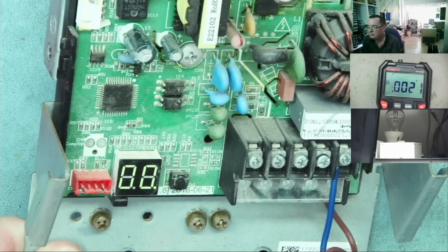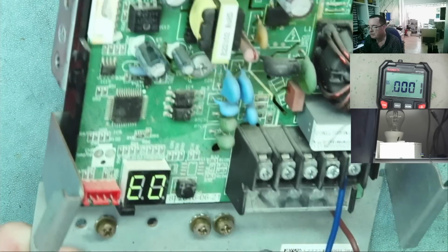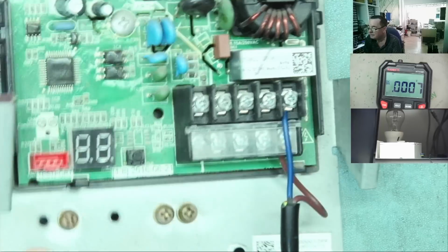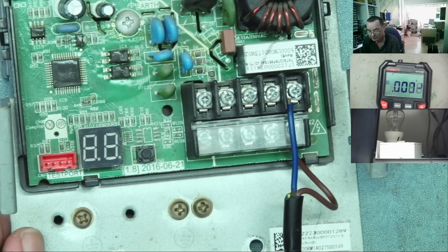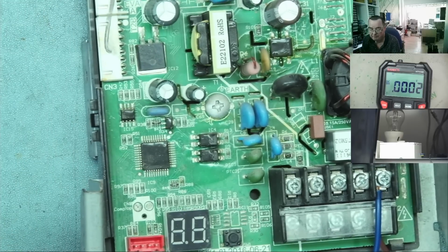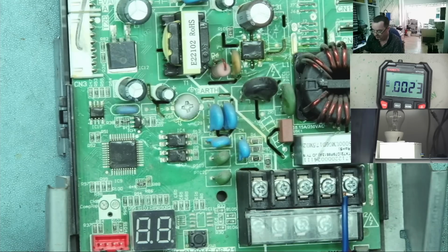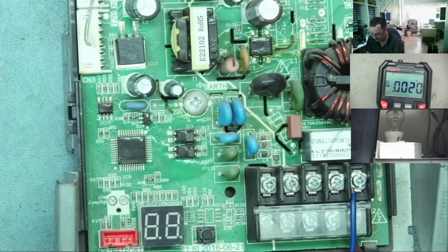Being an outdoor unit, that seems a bit silly if you couldn't see it, but I could not see that lit up. And yes, I know I had mains here because I measured it, I checked that on site. So maybe that's a red herring. Let's have a look at the other PCB, see if we can see anything obvious in the direction of that one. But with this one, well, the mains comes through to the output terminals and this powers up and runs. So I'm confident enough to say this thing is actually okay.